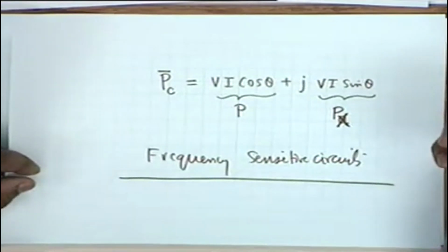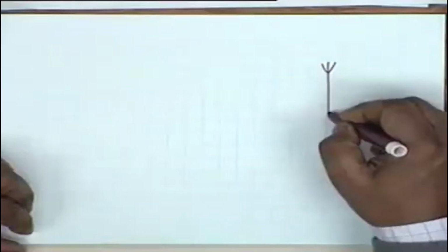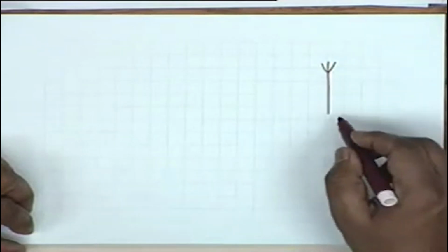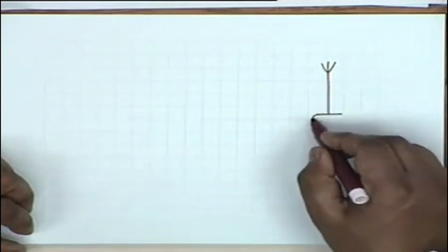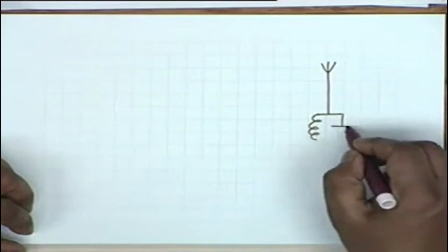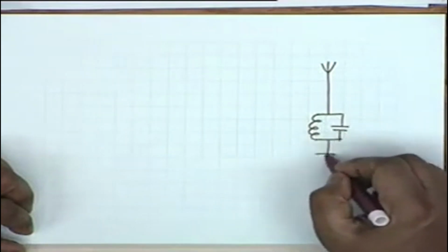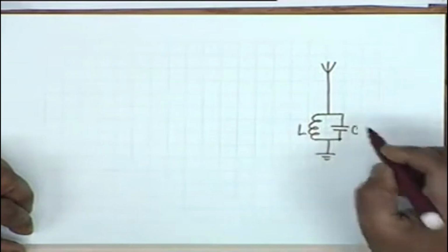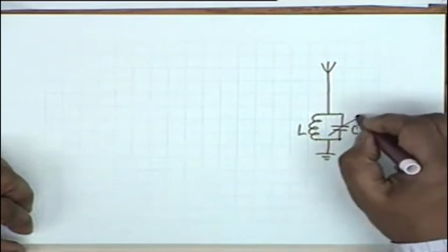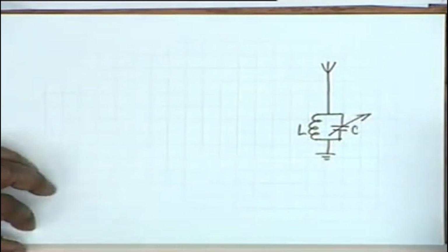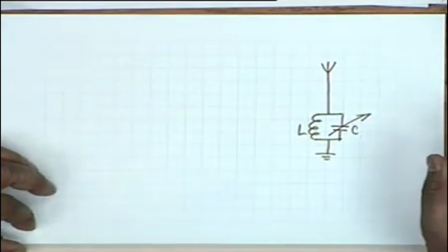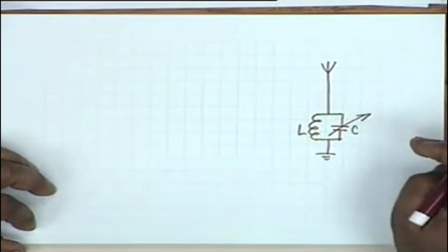All right. Now, what you basically do is different transmitting stations are transmitting at different frequencies, and what you basically do is, this is the aerial, you have an inductance capacitance circuit in parallel, L and C, and tuning, what you are doing essentially is rotating a capacitor knob, so you are varying the capacitance.